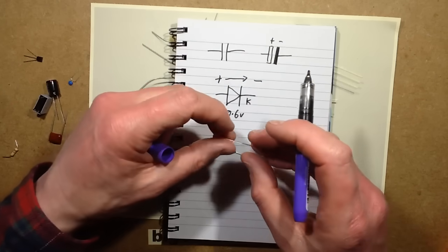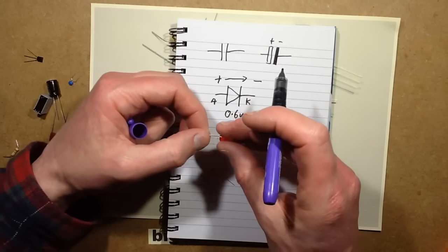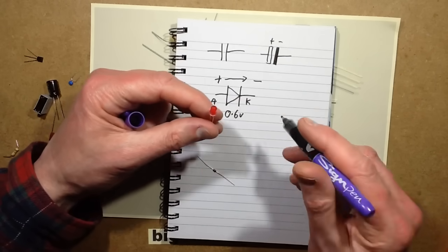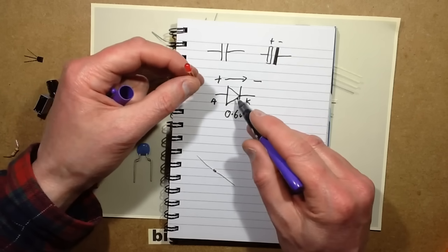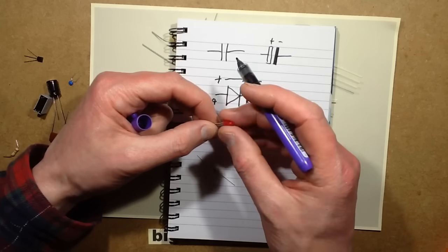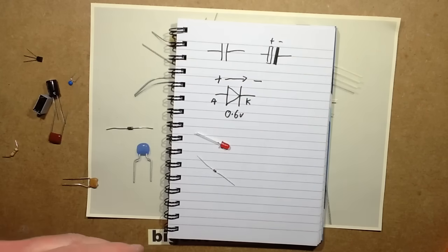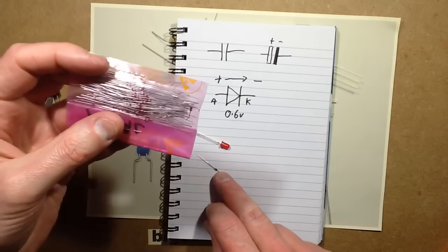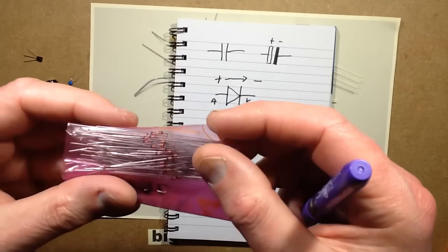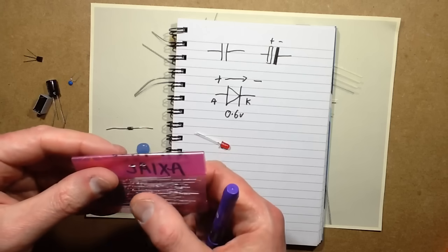The light emitting diode, our favourite type of diode really, is a diode junction that is optimized. It behaves in a way like a normal diode, but when it's forward biased, when the current's flowing through it, it emits light. And the very first LEDs were actually, here's some here, they look just like the 1N4148. These are actually LEDs. They look just like ordinary glass diodes, but these are really vintage LEDs.